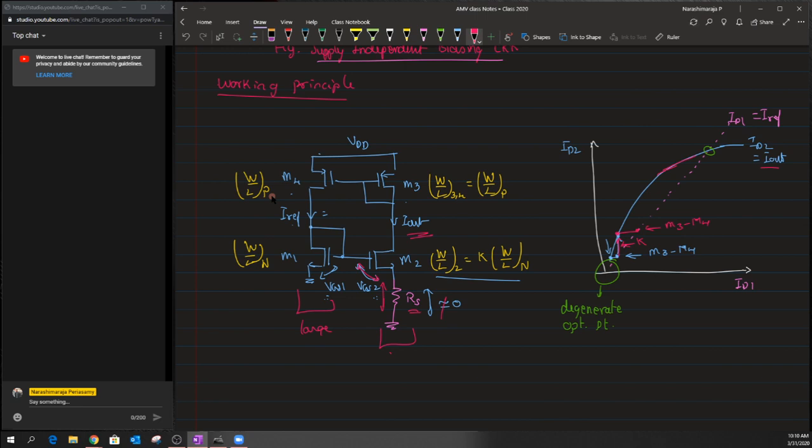And in that situation, one could consider that this entire structure is nothing but a CS amplifier with source degeneration resistance Rs. Okay, so previously, initially, it was just a CS amplifier with this diode connected load of M3. And then after we pass on to a certain value of current flow, the circuit was shifted from this configuration to this configuration as the drop across the resistance becomes a non-negligible quantity.